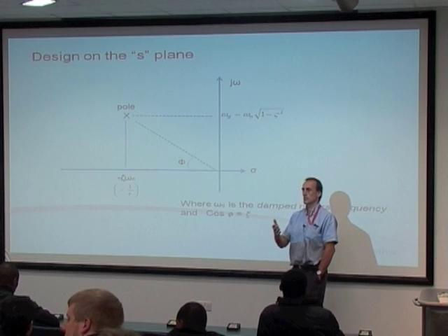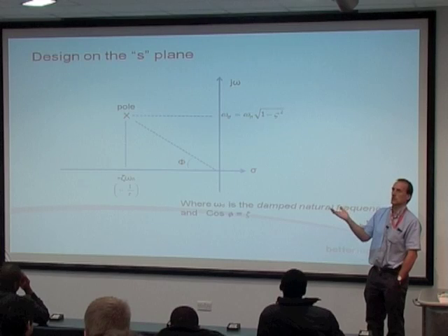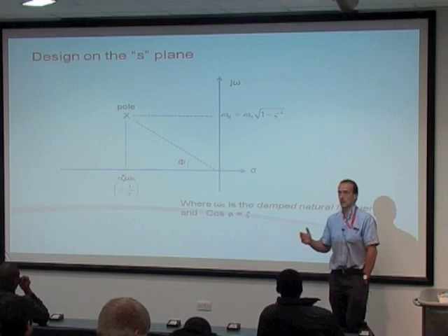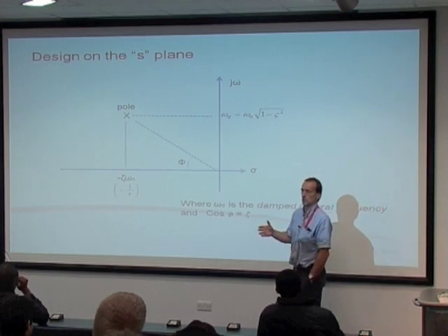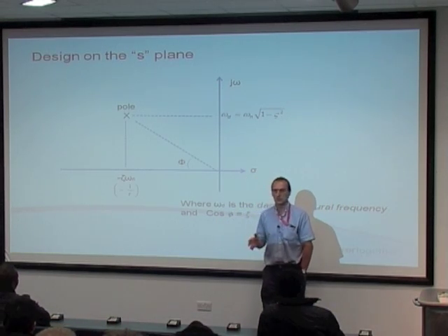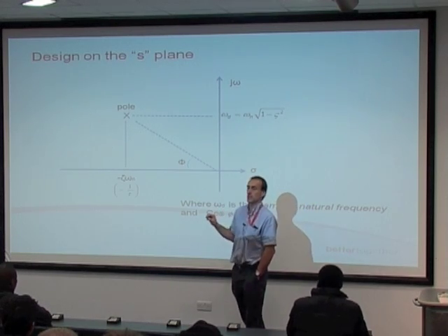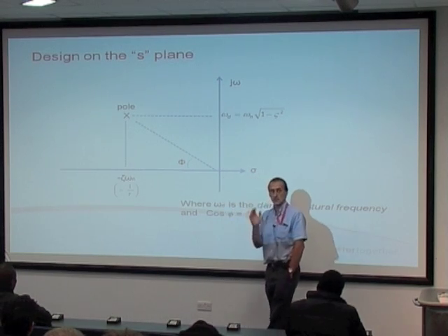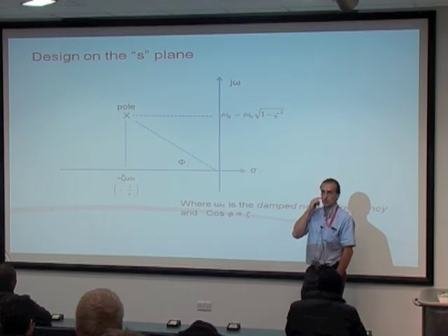That's right. It's the time taken for a system output to come within a certain percentage and stay within that percentage of the final value. And the definition for settling time, you might recall, there are multiple definitions. The one that I tend to focus on is the one where the output gets to within 5% and stays within 5% of the final value, the time it takes to get to that point. Do you remember what that was defined as in first order terms?